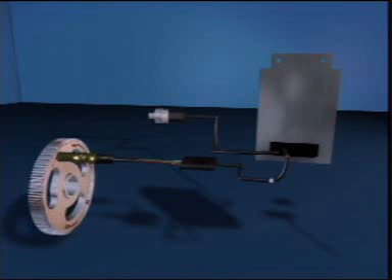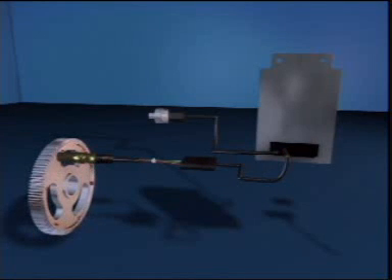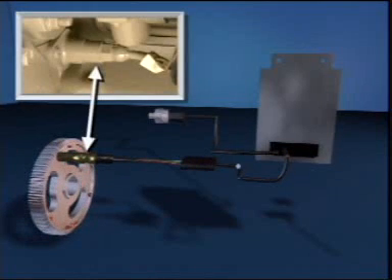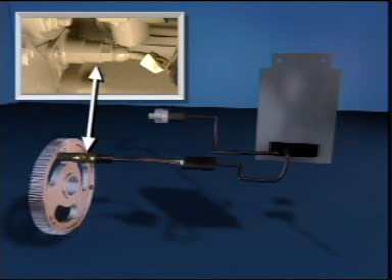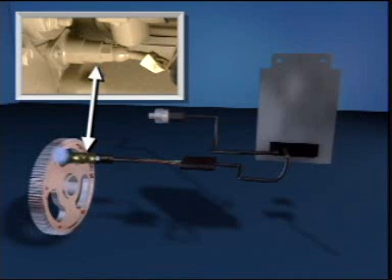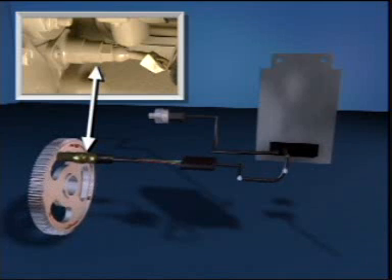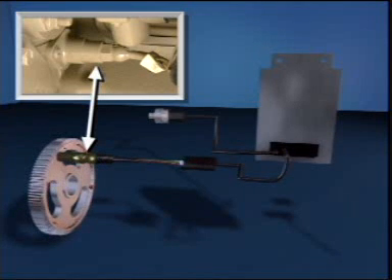6 of the 7 cast protrusions on the cam gear are located 47 crankshaft angle degrees before top dead center, 1 protrusion for each of the 6 cylinders. The engine position sensor sends a signal to the ECM based on these protrusions passing the end of the sensor. The ECM determines proper ignition timing and engine speed based on these signals.